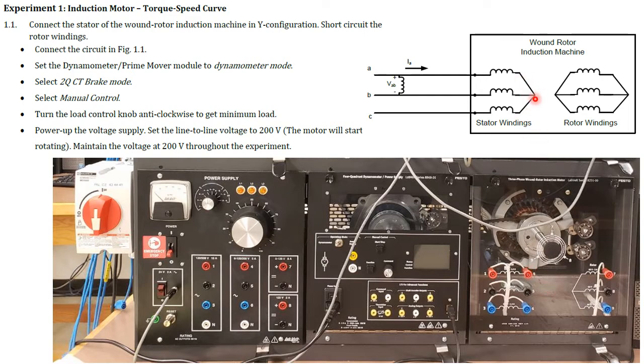And don't forget, you shouldn't connect this to anywhere else. Just connect these three together, that's it. You shouldn't bring this back, and don't do that. Then you should connect the other side of the stator, 1, 2, 3, to the three phase ABC. But don't forget, before that, you should measure the current. So for phase A, this must first go to the ammeter, then bring it here. And you saw in Lab 3 how to do it.